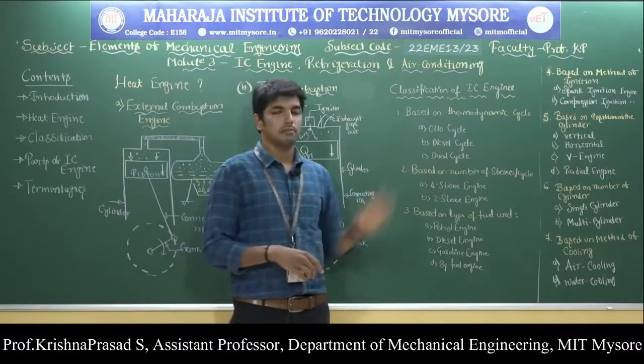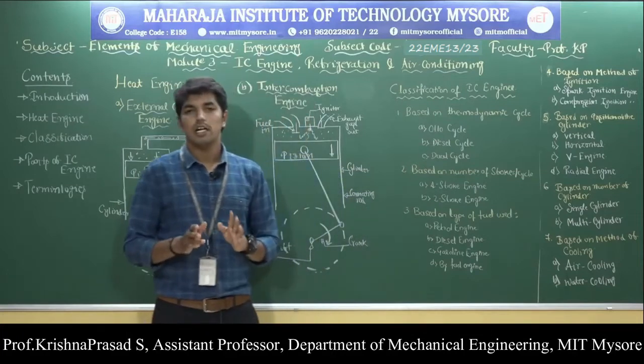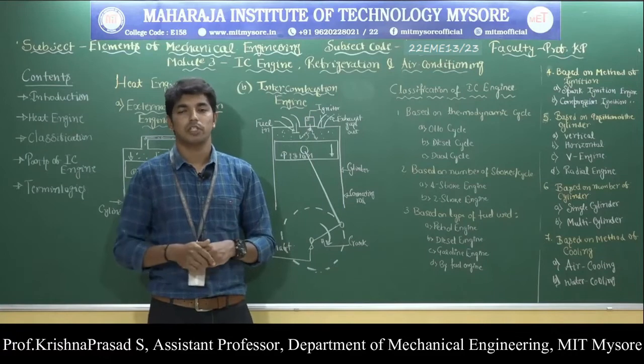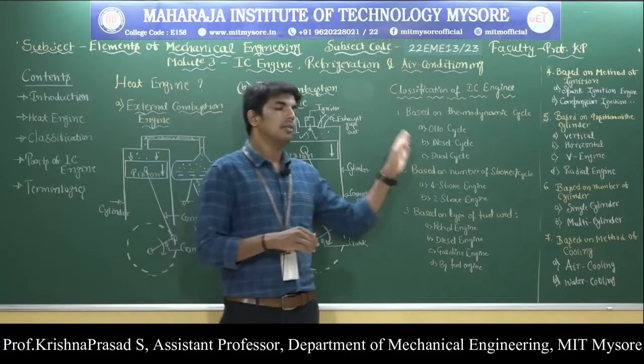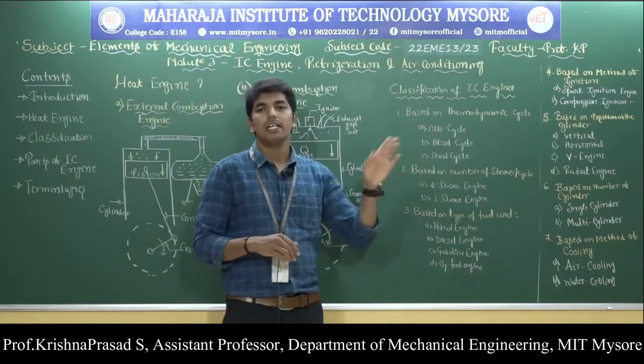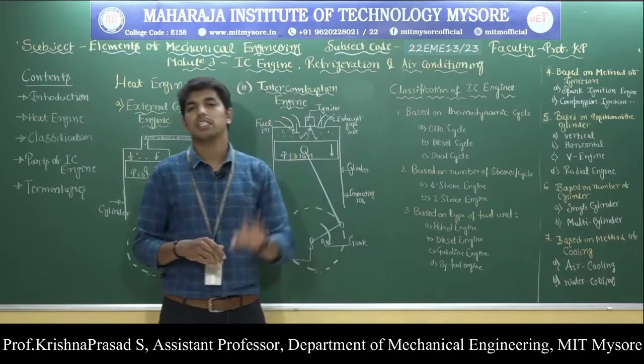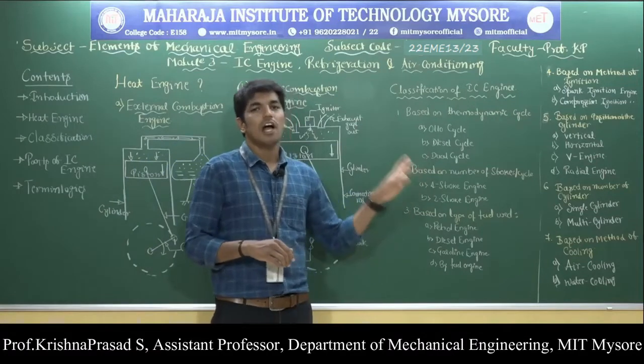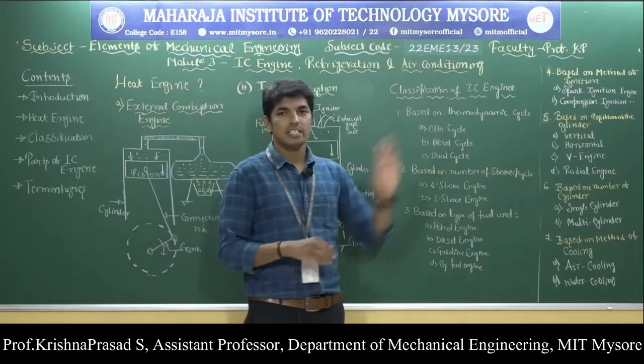Then the dual cycle. So what is meant by the dual cycle? Here combustion of the fuel takes place both at constant volume and at constant pressure. That means first the combustion of the fuel takes place at constant volume, and later combustion of the fuel also takes place at constant pressure. So this is regarding the classification of IC engines based on the thermodynamic cycle.